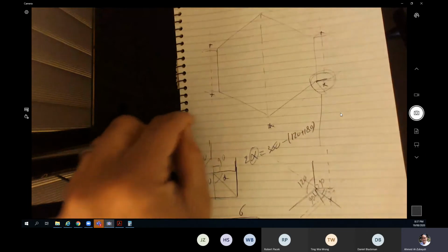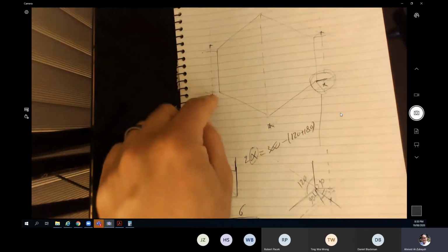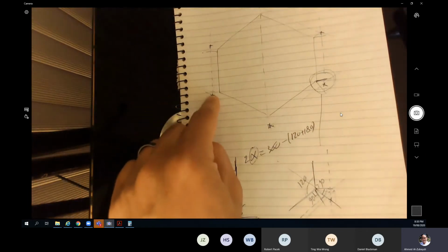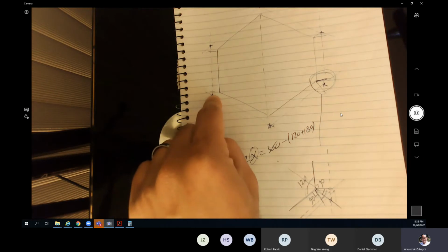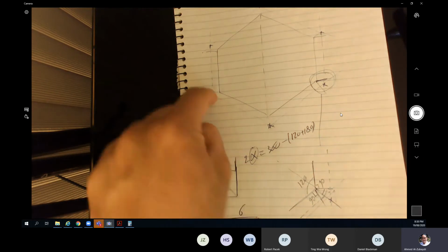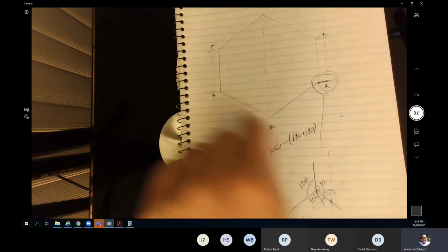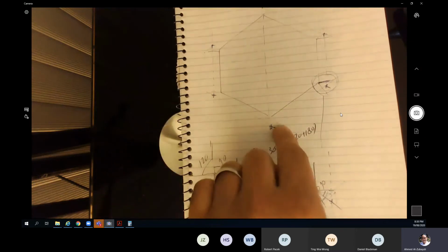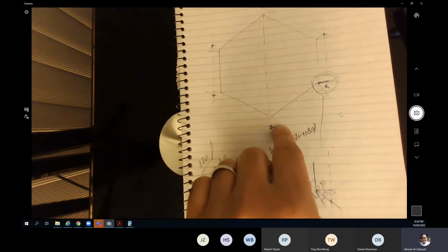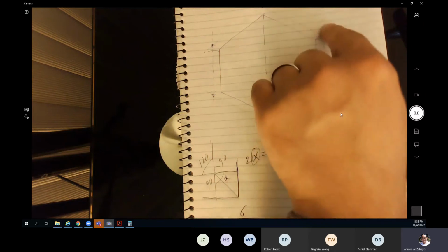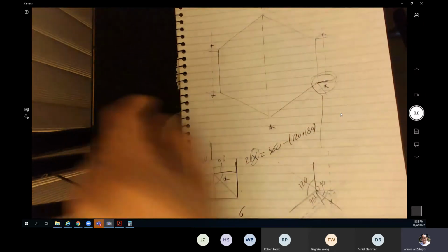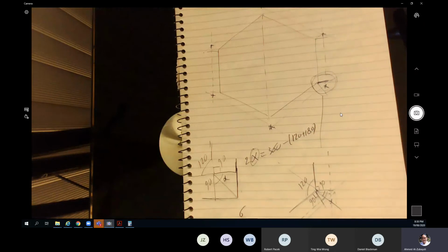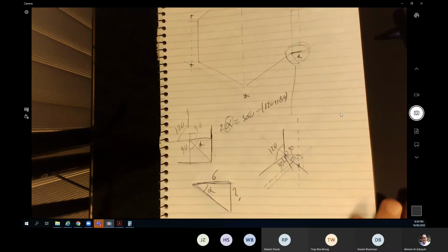Now bring the cutting tool. The G code is going to be come to the top of this one, drill it down to the total depth, which is minus 27 or minus 28.5. It's up to you. Then start to do the cutting by moving to this point, G01, G01, G01, G01, G01, G01, then G00, and leave. That's the only thing we need to do for the operation number 1, setup number 3.